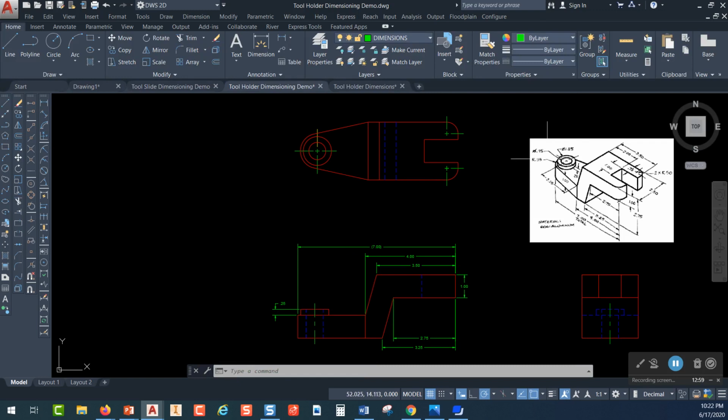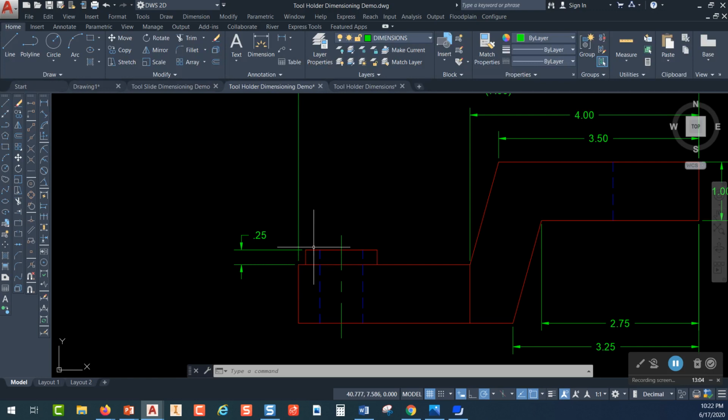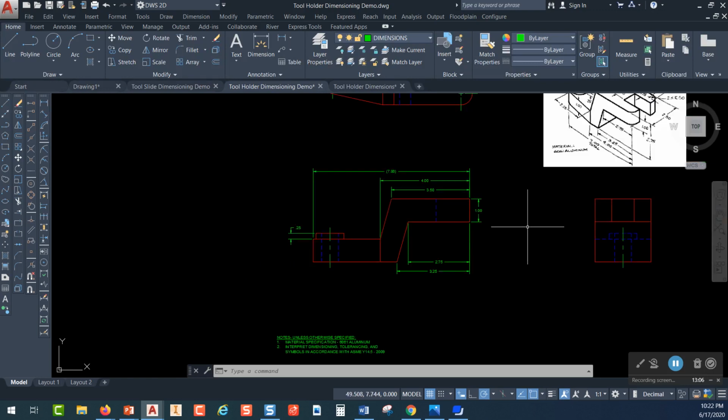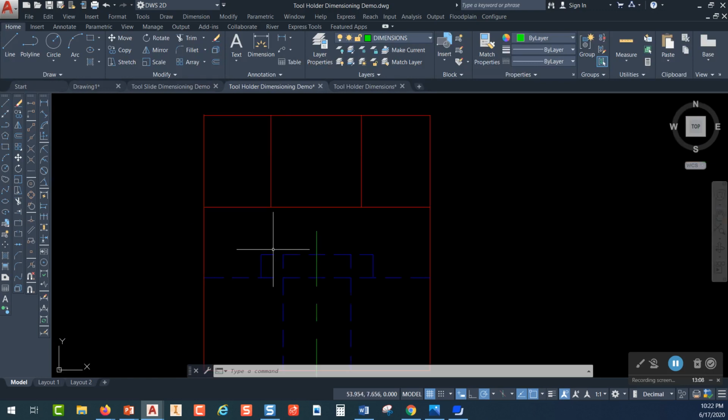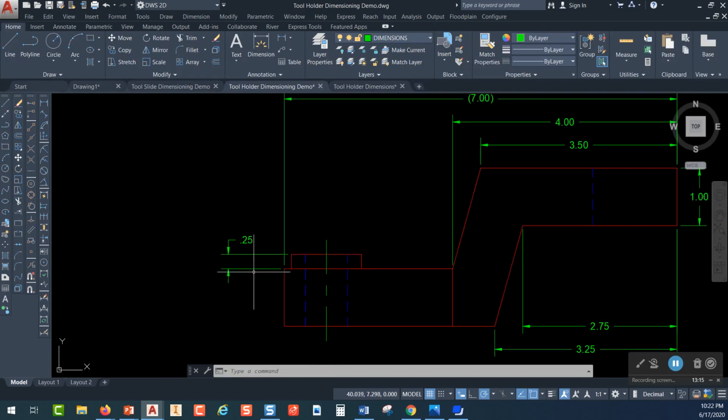You can see it over here on the sketch, and this is it in its top view. And so we wanted to use the profile view to show the height of that. And even though we might be able to see it over here, we don't dimension to hidden lines. So there it is sticking up, but all those are hidden lines, and we avoid dimensioning to hidden lines.